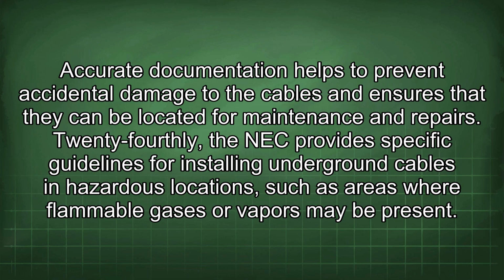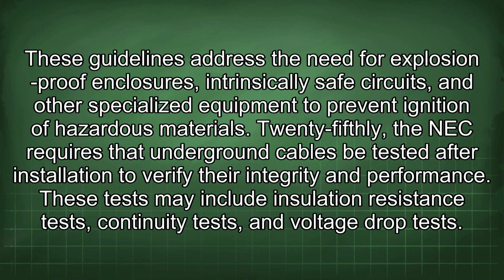for maintenance and repairs. 24thly, the NEC provides specific guidelines for installing underground cables in hazardous locations, such as areas where flammable gases or vapors may be present. These guidelines address the need for explosion-proof enclosures, intrinsically safe circuits, and other specialized equipment to prevent ignition of hazardous materials.